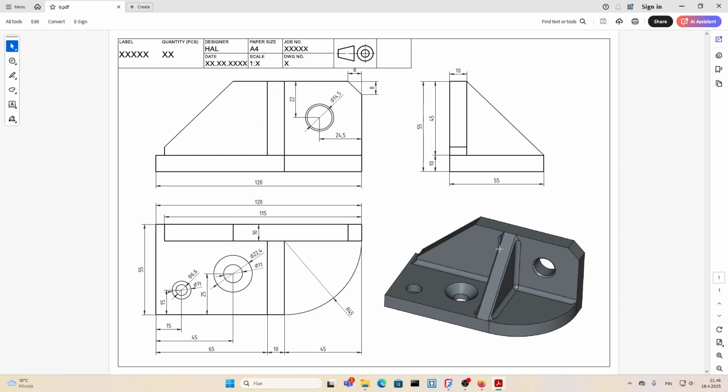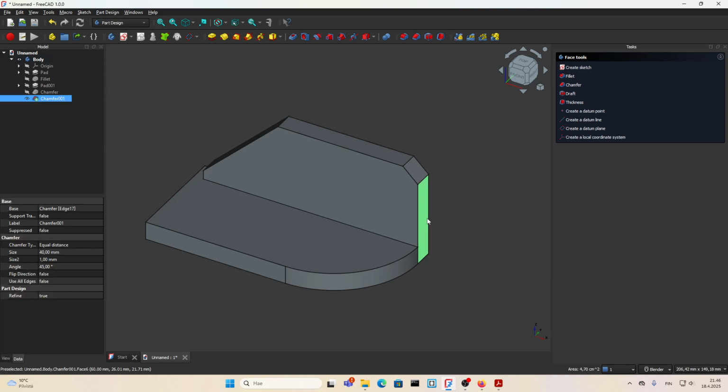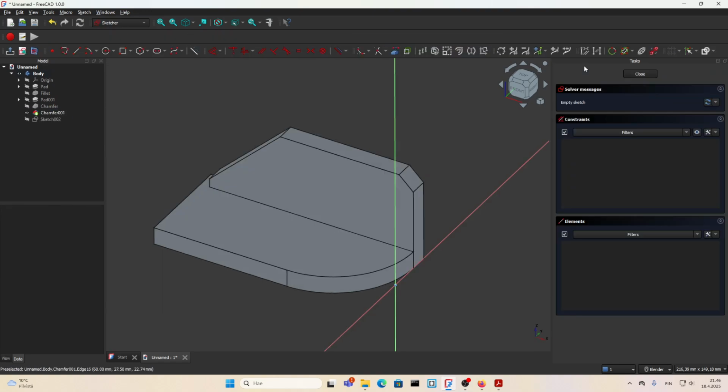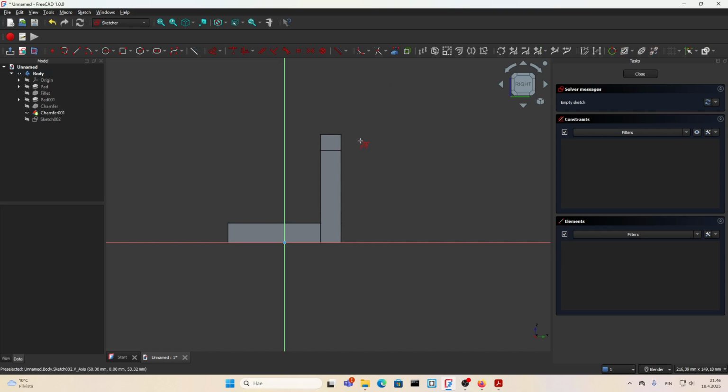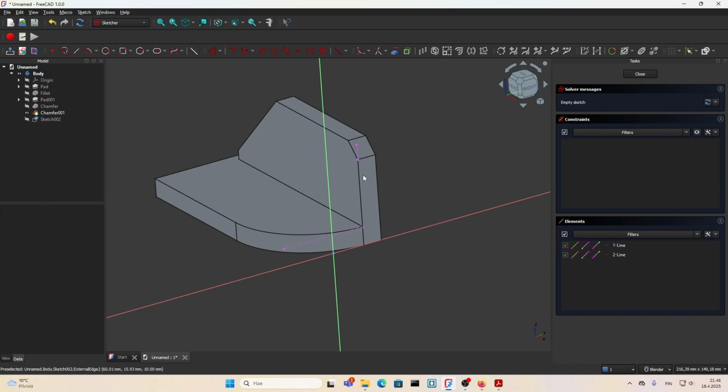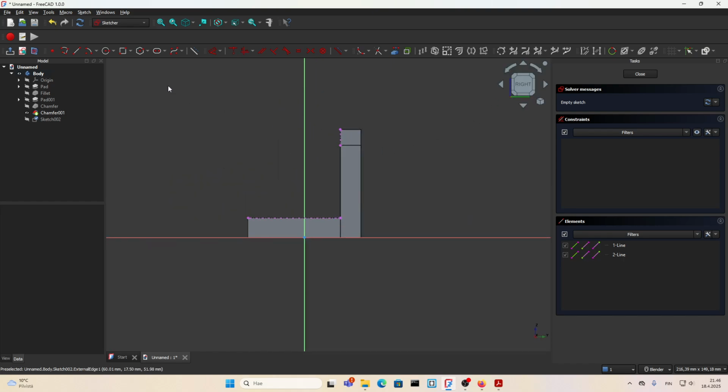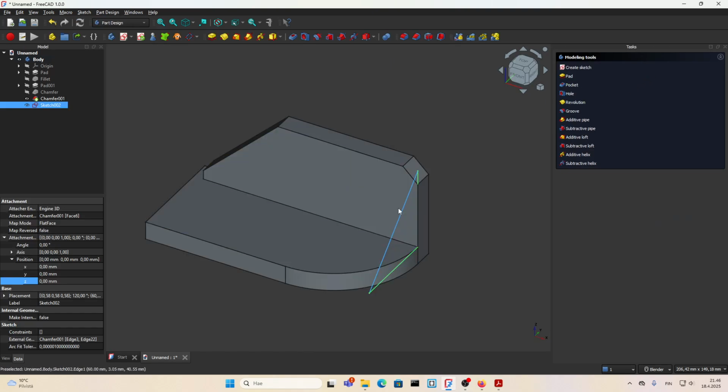then let's go back. We have this piece in here from there to there, and the thickness is 10. Choose the plane that you want to create a sketch on. Create a sketch. I need external geometry in here. Also, I need external geometry in here. Right click, exit the tool. Here's my external geometry. Let's go back. Follow line from here. Choose this dot, this dot, this one, and close it. Right click, exit the tool. Fully constrained, close it. Here is our sketch.